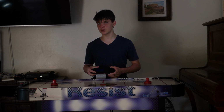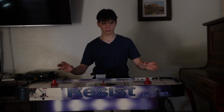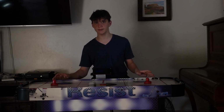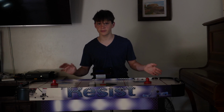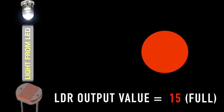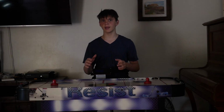This program makes use of the Arduino's EEPROM also by saving score values, because of how each score box works. There's an LED in both of them, which is white, and then there's a light sensing resistor. This resistor reads how bright the LED is, and usually it's around 15 on the ADC value, which is analog 1 and analog 2, etc. And basically, when the puck, which is this, goes through the score box, it blocks that light. It can be really quick, but the analog pin will actually sense that.